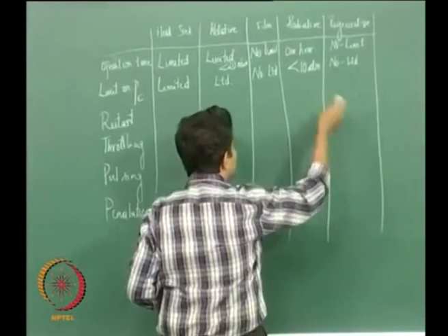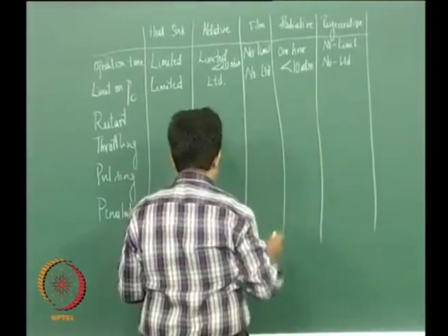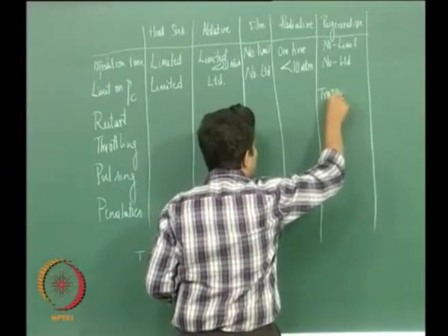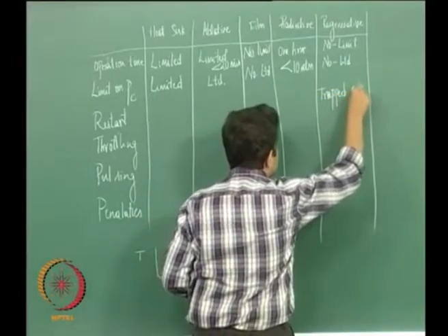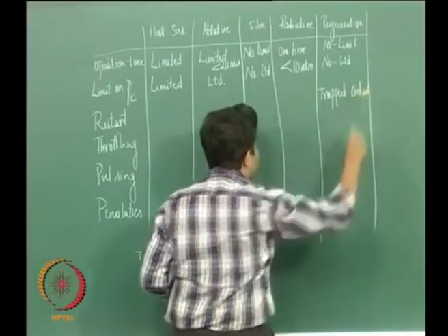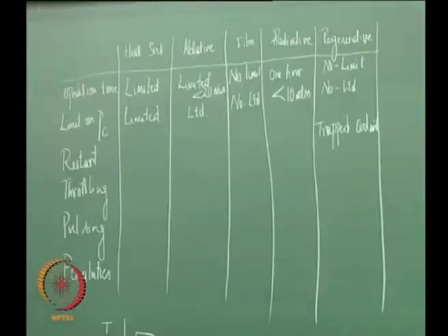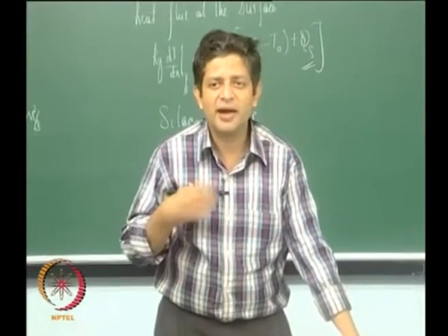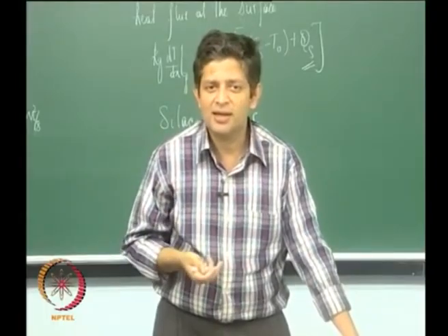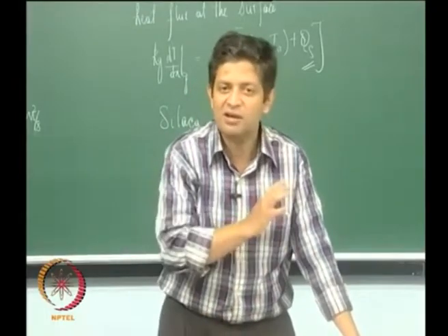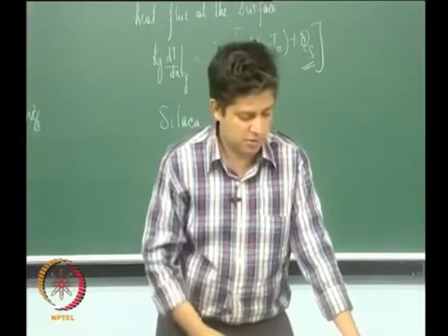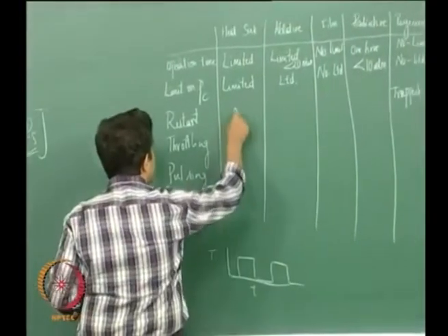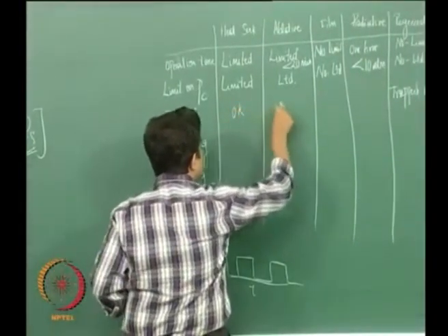So you cannot have too many restarts if you have regenerative cooling. Till the time it reaches some kind of steady state, the flow will not be established, and that might cause harm to the motor casing itself. So you need to be careful while using regenerative cooling, but otherwise for the rest it is fine to have as many restarts.